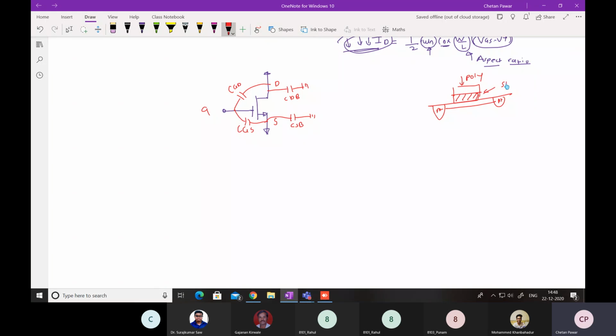This is the silicon dioxide, which is a dielectric, and this is an N-type channel. Okay. So in this also it forms a capacitor. So for MOSFET, gate capacitance is very important. So a MOSFET generally is a capacitor, but we extended that capacitor to work like a transistor. Okay. So different capacitance values are there.